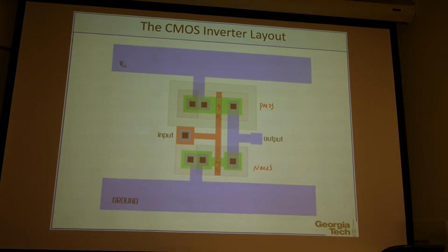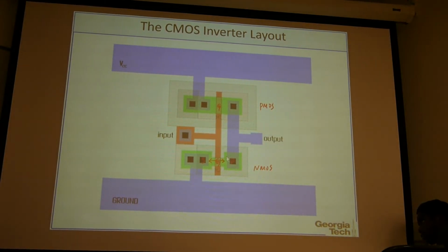And then this is like a top view of the transistor. So you have the gate here, and then that means you have source and drain like this, and your channel is along this direction. The red region is the gate wire, and the green region is your doping region, and this black square is a contact wire from the bottom tier to the upper tier to collect vertically.